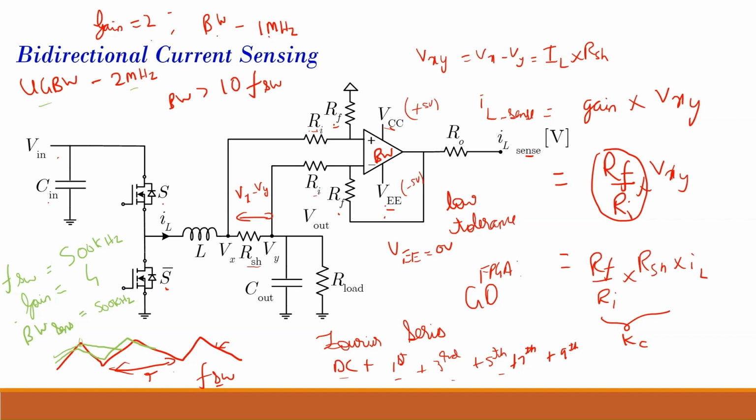Another thing is that noise will be there, and other things will be there, so it would not be sufficient for you to control. There will be issues in controlling it. Sensing is a very difficult thing to debug. Your control is useless if your sensing is bad. You might have a very good controller and a sophisticated algorithm, but if your input signal to the controller is poor, the performance will obviously be poor.